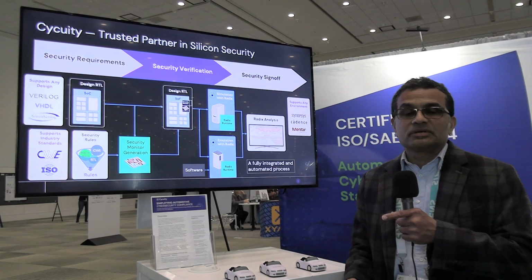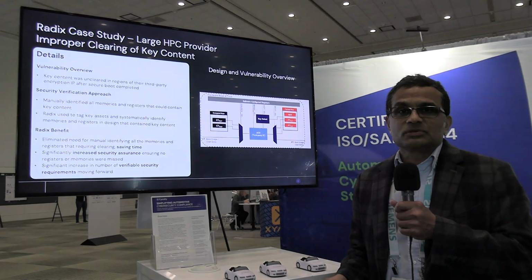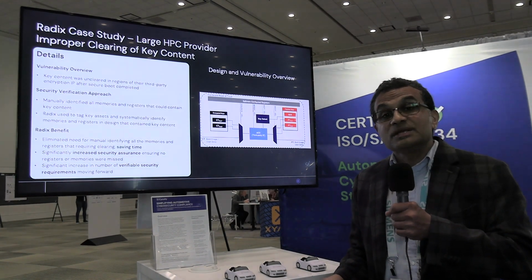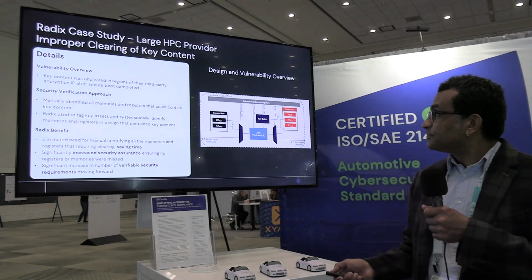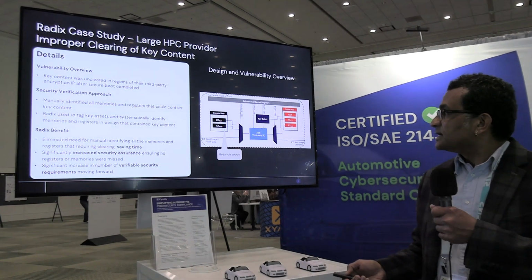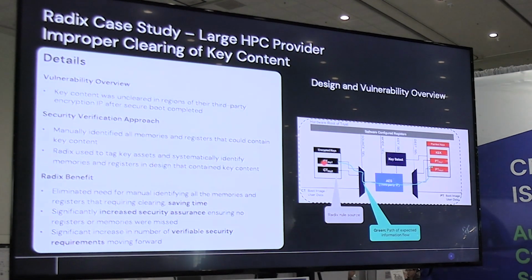Next, I'm going to talk about an actual customer case in which we found security weaknesses in an existing design. So here we have an AES block that can take cipher keys, decrypt them and then store them in this plain text key table that can be used later on to convert your user information through the AES block and then use it later on in your boot image.